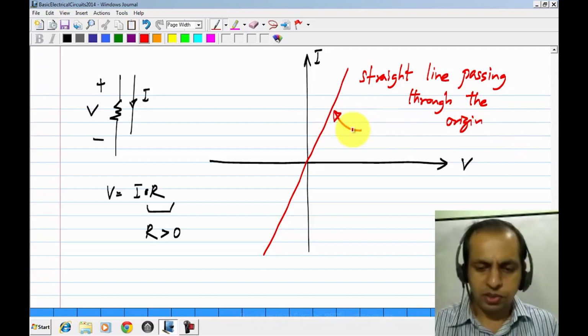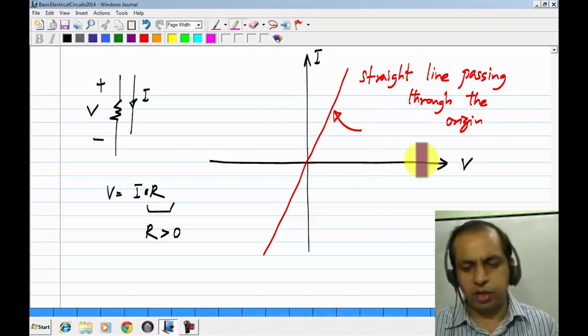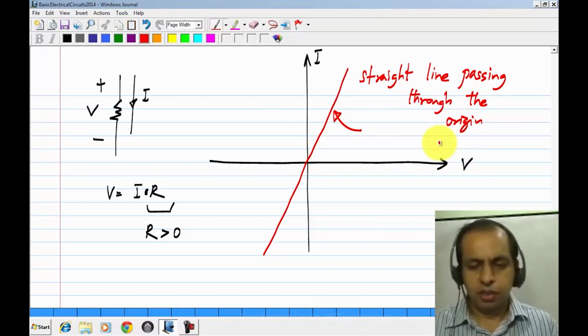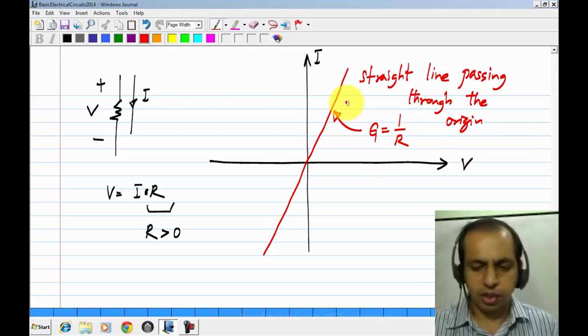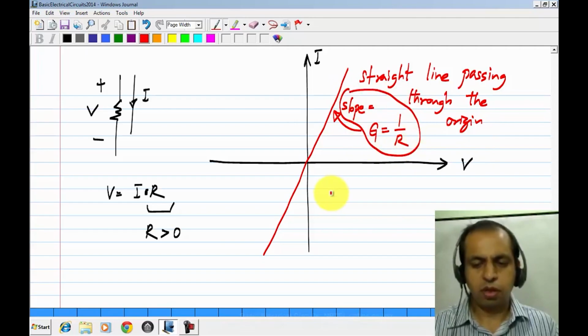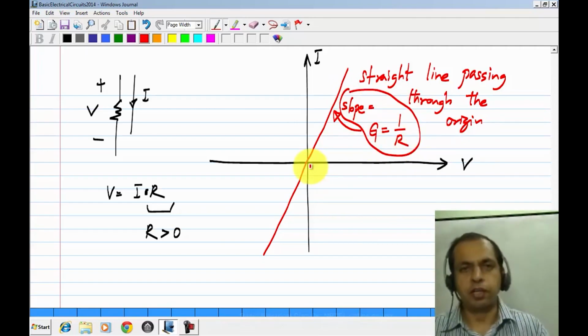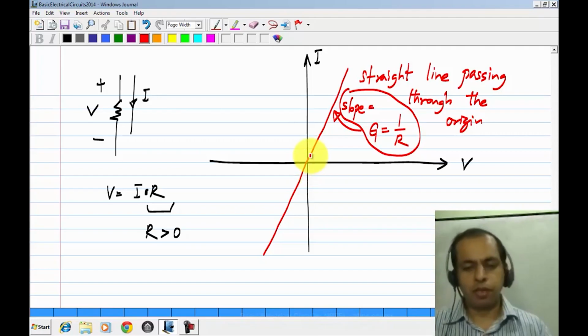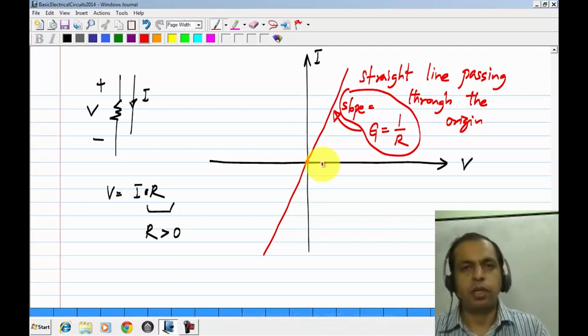and the slope of this, remember we are plotting I on the y axis and V on the x axis, the proportionality constant is the conductance or the reciprocal of resistance. If you had plotted V versus I, the slope would be the resistance. So, many times you can use this graphical characteristics to either visualize intuitively some solutions or even sometimes carry out the calculations.